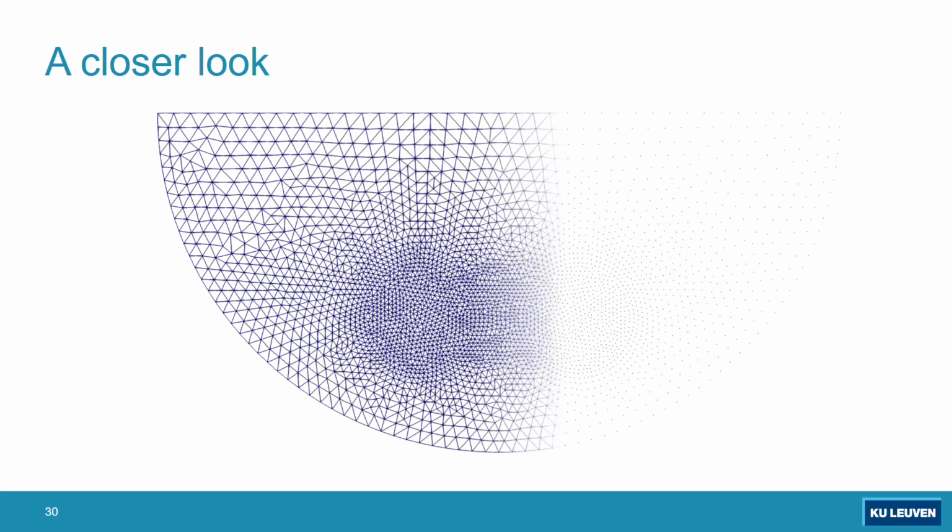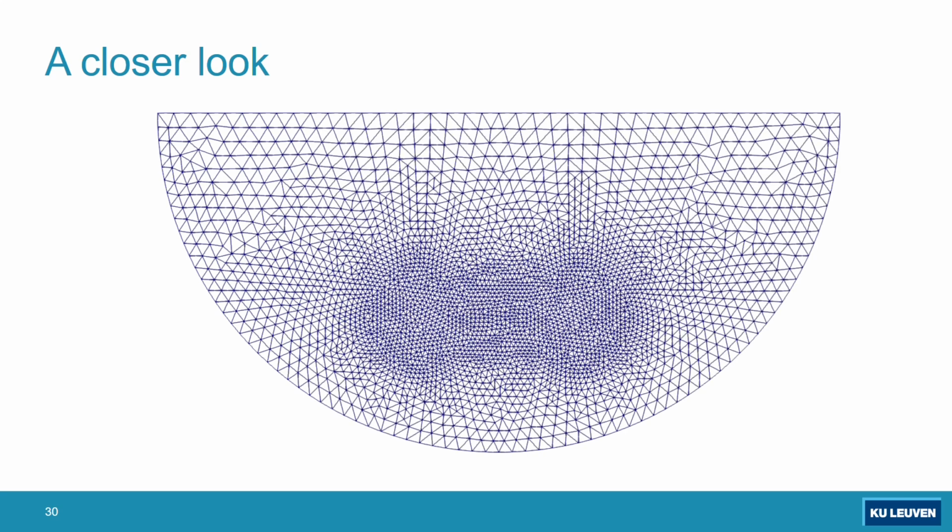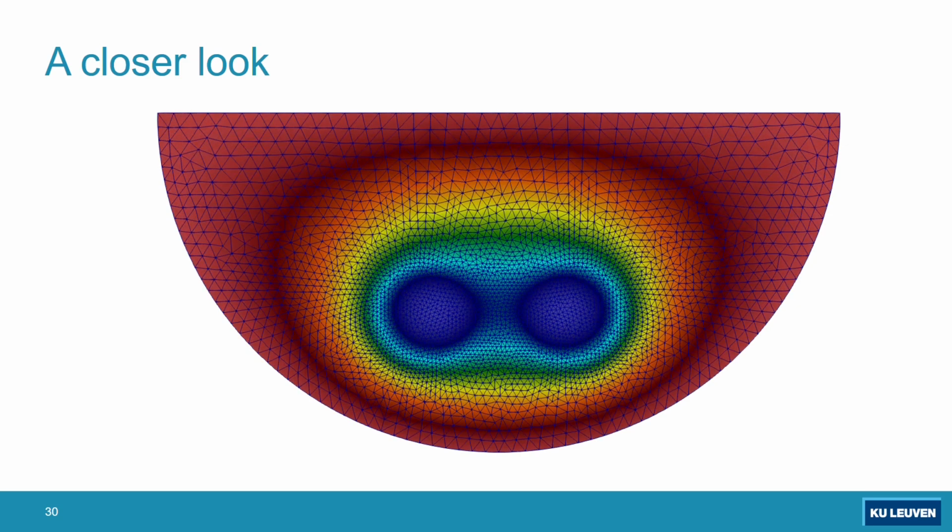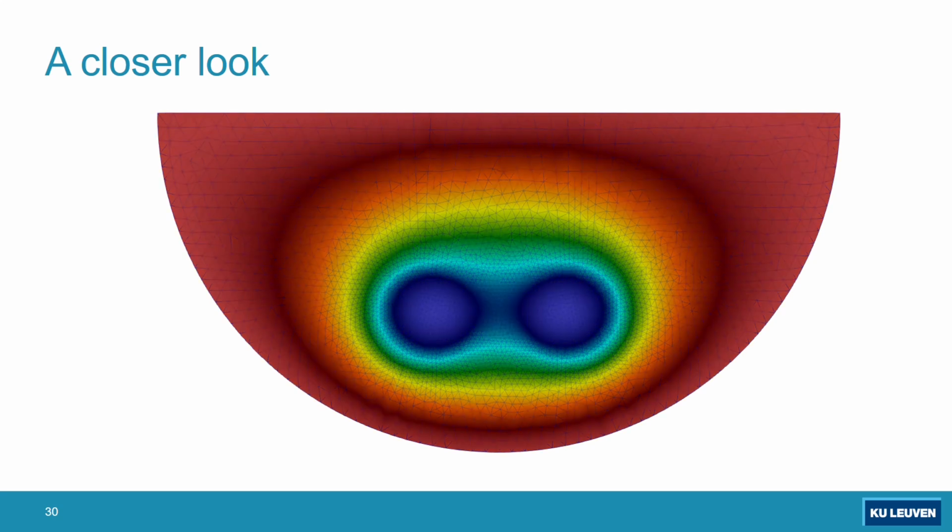And then what you see as elements, we call a mesh or a grid in finite elements or other numerical methods. That's actually connecting these points together, as simple as that. So what you see is the points connected to each other. And then we solve the equation here. So it becomes something like this: the concentration of oxygen due to the consumption of it. And then we just omit the lines. This is what you see in presentations when we present something. This is actually the solution. And when it is over time, that will be similar to the animation that you saw in the previous slide.